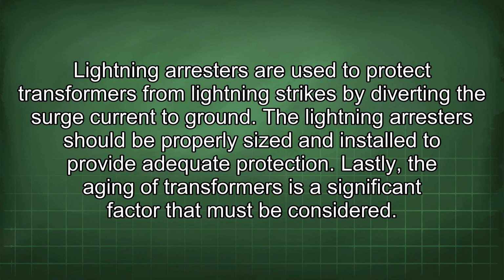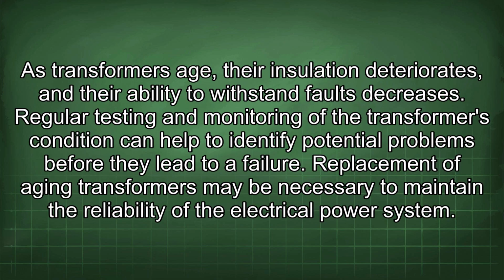Lastly, the aging of transformers is a significant factor that must be considered. As transformers age, their insulation deteriorates, and their ability to withstand faults decreases. Regular testing and monitoring of the transformer's condition can help to identify potential problems before they lead to a failure. Replacement of aging transformers may be necessary to maintain the reliability of the electrical power system.